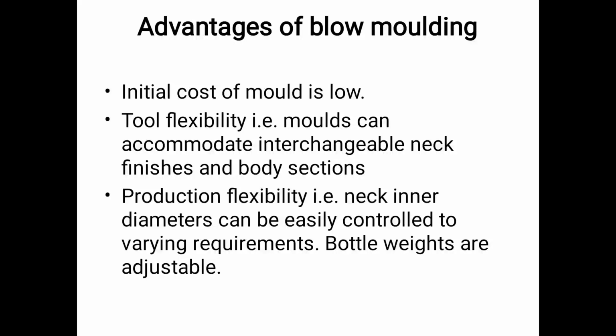Then the advantages of blow molding: the initial cost of the mold is low. Tool flexibility, that is, the mold can accommodate interchangeable neck finish and body sections. Production flexibility, that is, the neck inner diameter can be easily controlled to varying requirements. Bottle weights are adjustable.